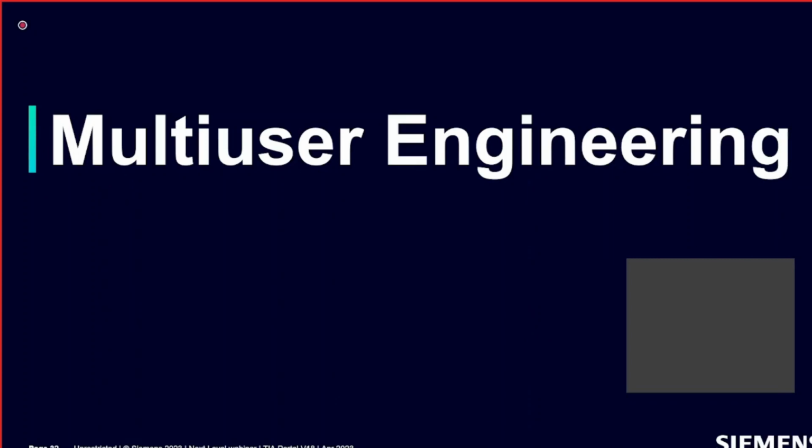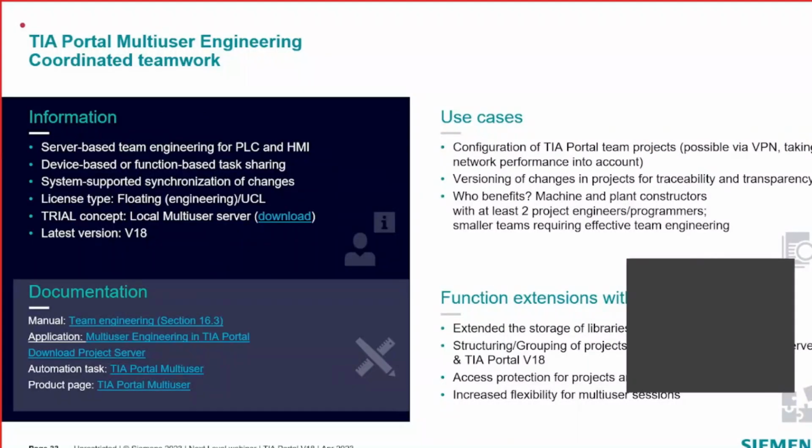Moving to the next topic, multi-user engineering. For those who are not aware of it, I'll give you a brief. With multi-user engineering in the TIA Portal, you can work with multiple users together simultaneously on the same project. In order to work simultaneously with several users in a multi-user server project, each user has to create their own local session.